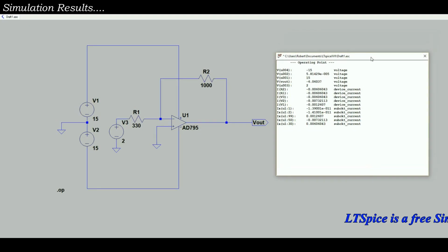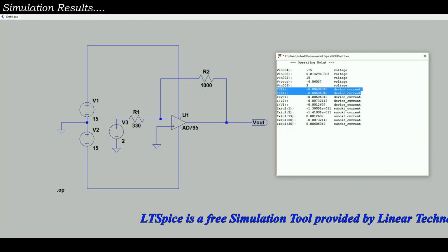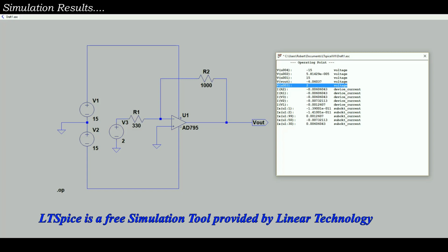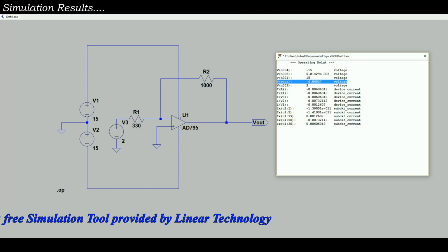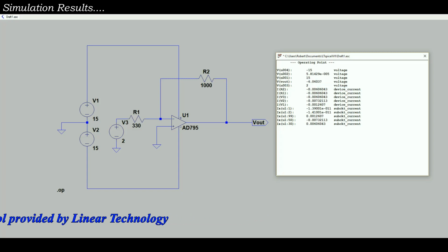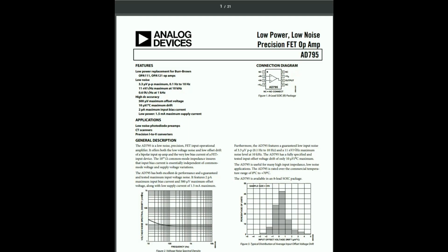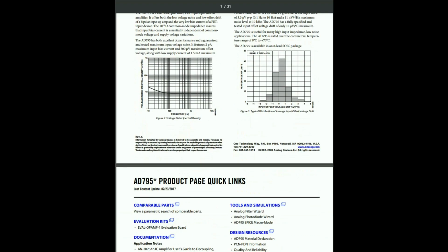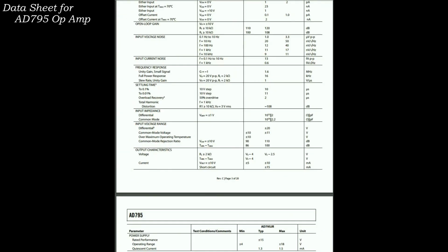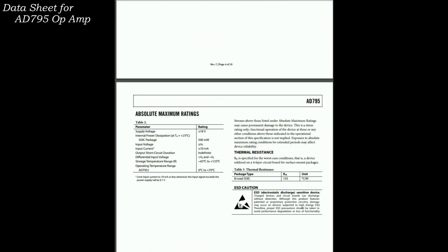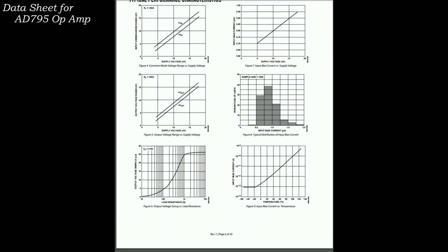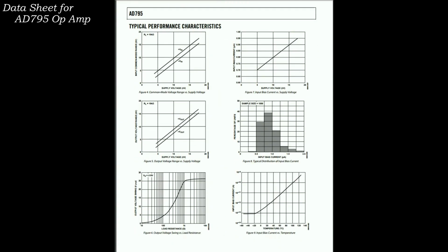We're going to look at the simulation results here in LT Spice, and they're pretty consistent. Now with this particular model, if you increase the input voltage, you'll get a little different result. It's not linear. We're not going to go into that. We're just looking at an ideal op amp model here, and for the purpose of this, it seems to work.